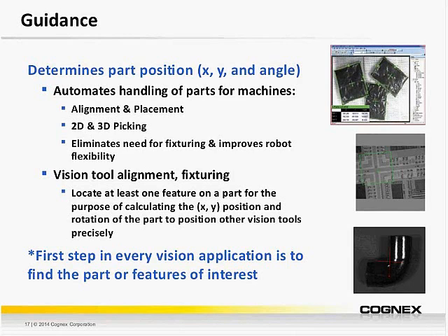into a process. Another type of guidance application would actually be used for large part inspection, such as using a robot to either manipulate the part or the camera to inspect critical features of the large part or assembly. The key advantages of vision-guided robotics are elimination of costly fixtures to reduce capital investment and improve productivity and manufacturing flexibility for mixed model processing, which essentially allows manufacturers to make multiple products on the same production line.